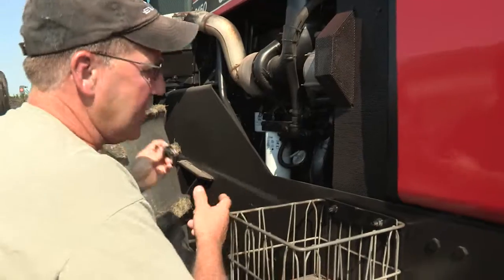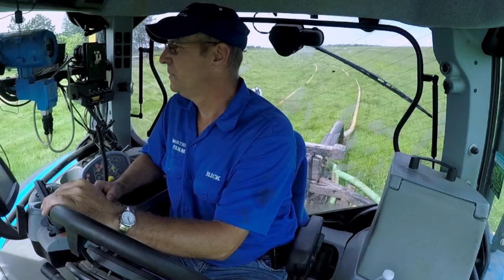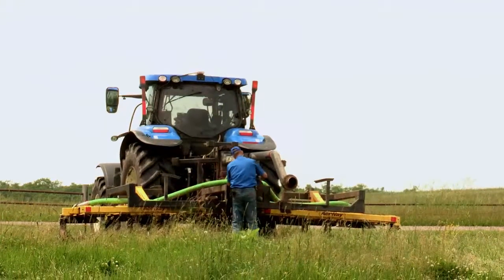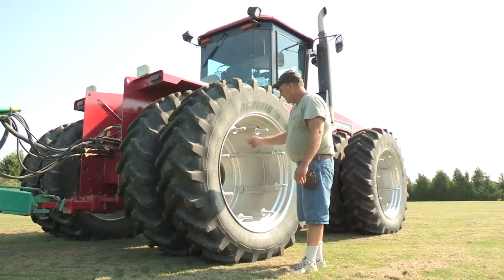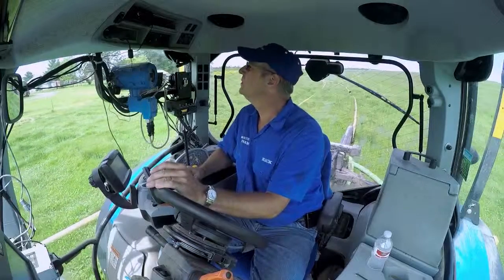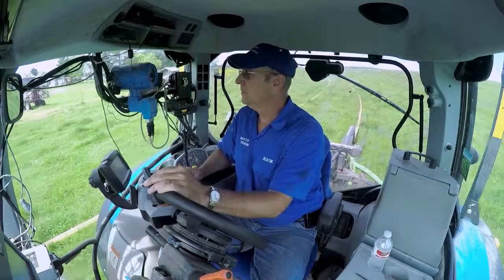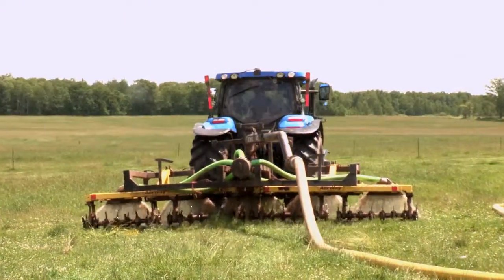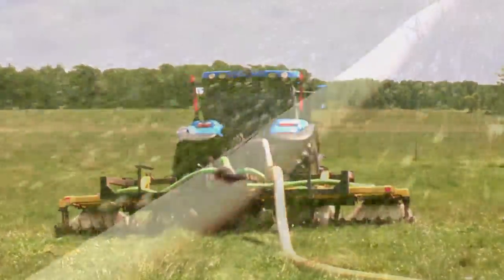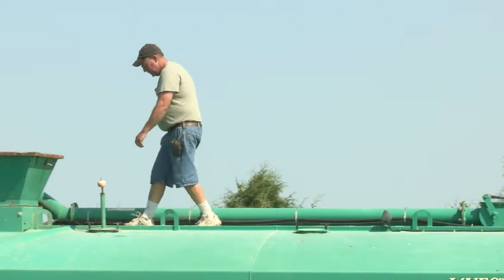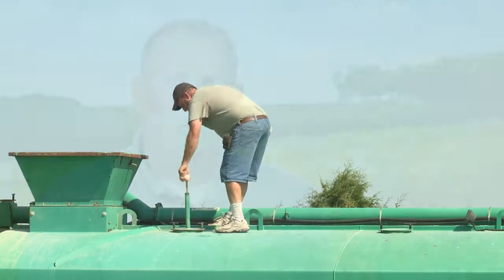As we said before, you hold the responsibility for knowing your equipment and maintaining it as needed. That means before you begin work, walk around the tractor and other equipment for a brief inspection to make sure all the signage is clean, all the lights are working, and the tires are good. Watch for wear and know when parts should be replaced. As you're driving, make sure everything is operating correctly and the meters show what you expect to see. If you're using a liquid hose drag, walk or drive an ATV to inspect every inch of the hose. The site manager may be responsible for maintenance and part replacement, but you're responsible for knowing the equipment you use and flagging problems for your site manager to address.